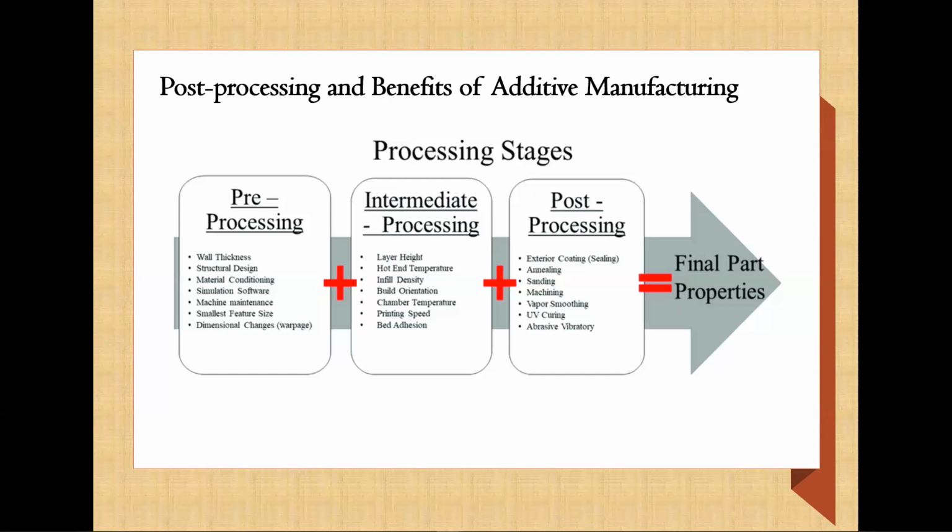The main consideration then for these materials are, do these contain the same material properties as their as manufactured counterparts, or is there a post-process step like one of the ones listed here in either the pre, intermediate, or post-processing that can be taken to get these material properties like these reference points for the wrought material or as-built material composition in a relatively simple process.